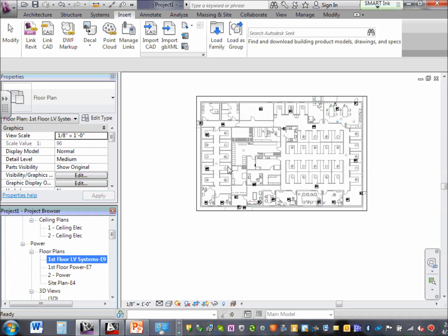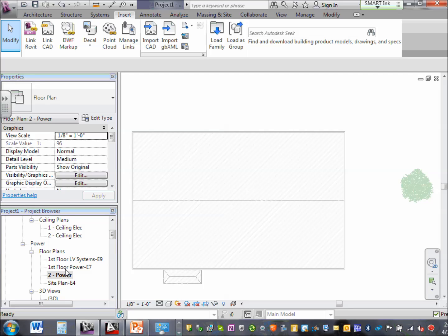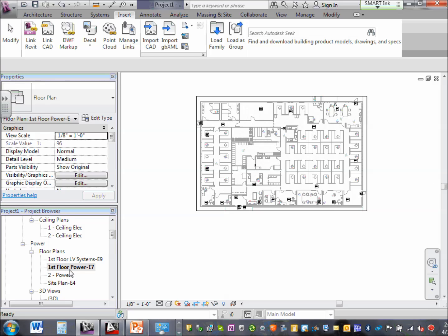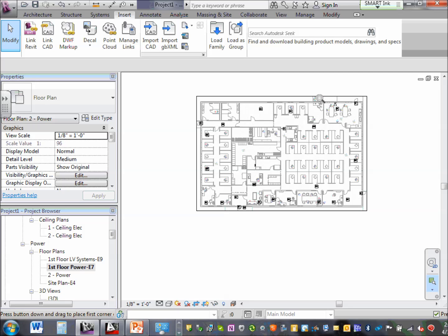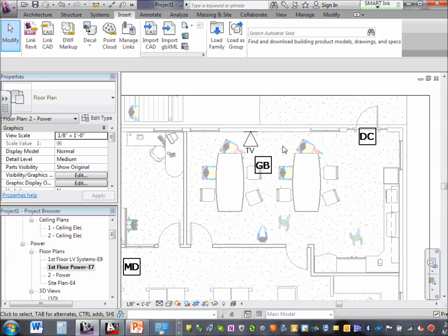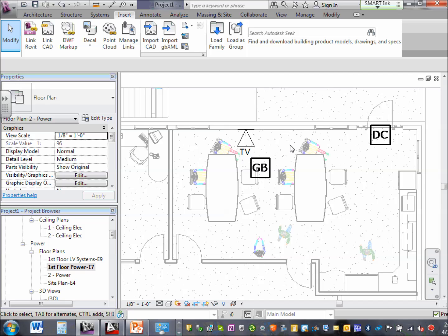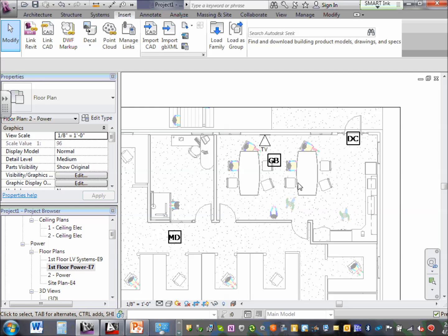Now, how are we doing on time? I'm going to do one more thing. We did the views, gentlemen. I'm just going to go to power and show you how easy that is. Let's go to first floor power, shall we? I'm going to drop one receptacle, gentlemen. Before you drop a receptacle, let's zoom region. Are you in zoom region here? I'm going to zoom into just that area. Can you guys see that area here? I'm going to zoom in on this kitchen. And remember, we can clean these at all times.